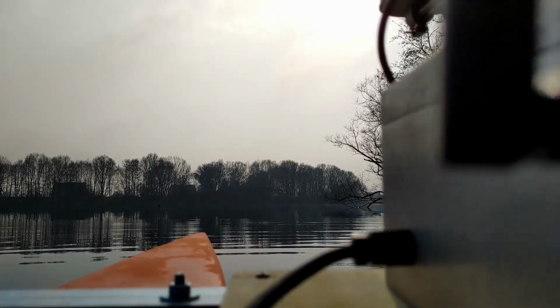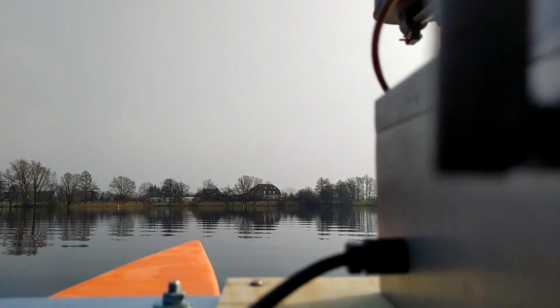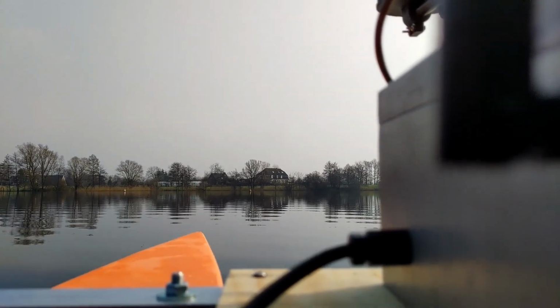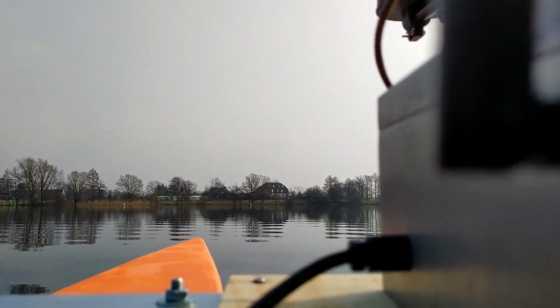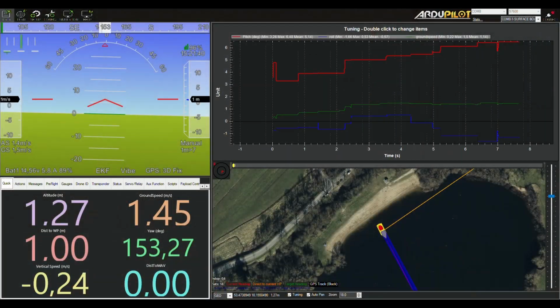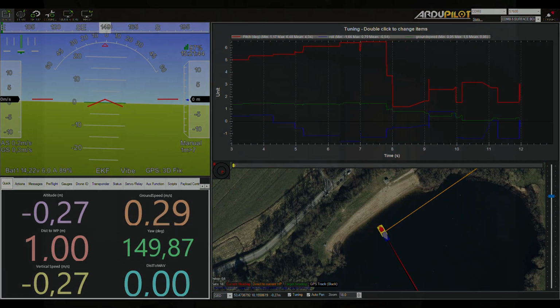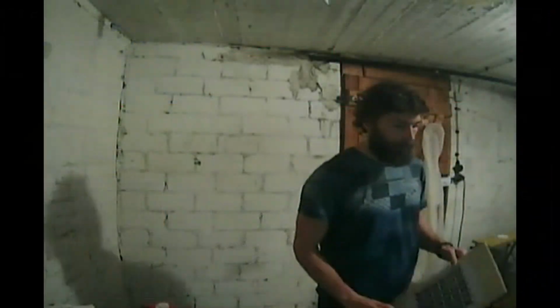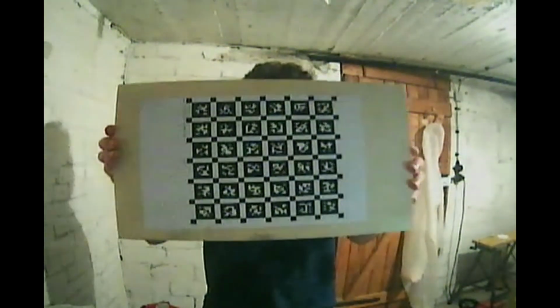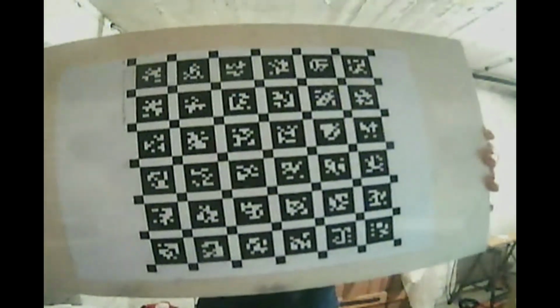To test our methods in a simulation and create synthetic training data, we need to create a simulation environment, duplicate the motion and control of the vessel, and simulate the characteristics of the camera on our USV. To do this, we first collect telemetry data from the USV. We then calibrate the camera in order to replicate its distortion characteristics.